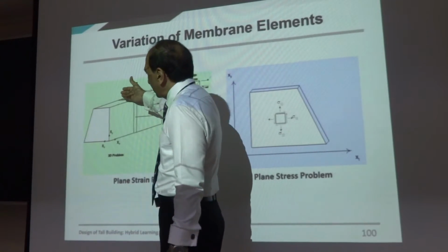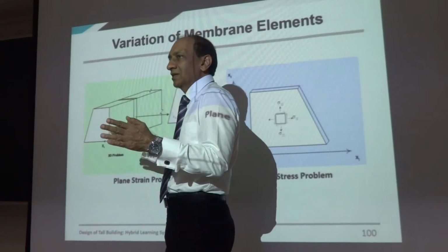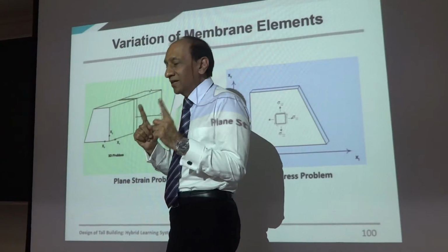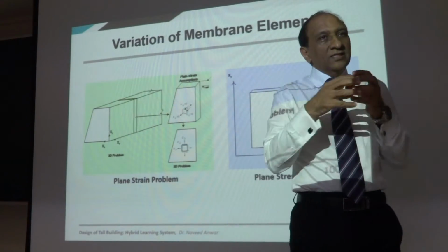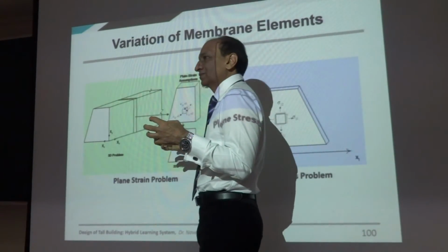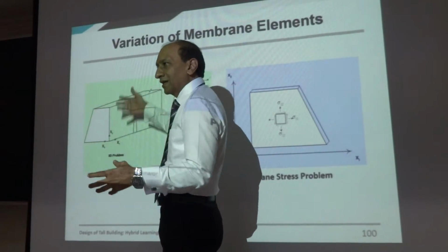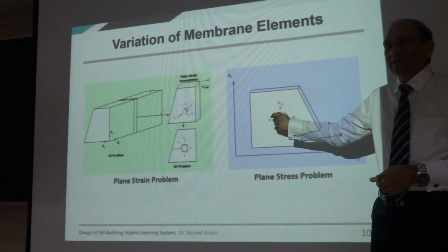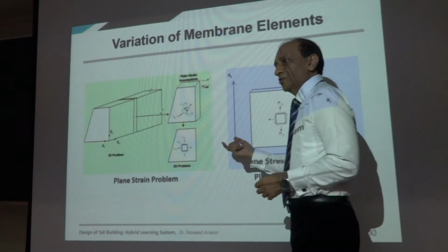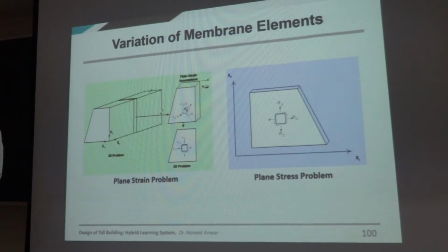We can also use a dam and model the dam by using similar technique, because all the sections are the same. Now, there are two interesting things here. In this case, perpendicular to this element, the strain is 0. There's going to be no strain in this direction because it's discontinuing. So you can cut that out. Here, the stress perpendicular to that is going to be 0. There's no body outside, right? So either way, if the strain is 0 or stress is 0 perpendicular to that, you can model it by the membrane type of element. If any one of them is not true, you cannot.